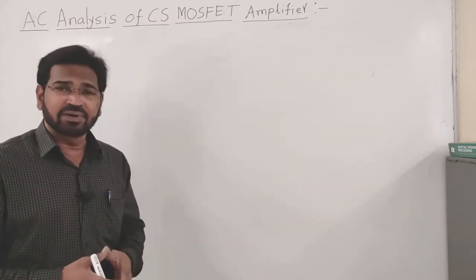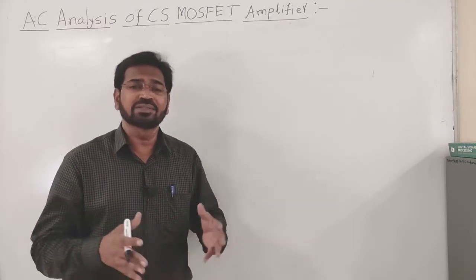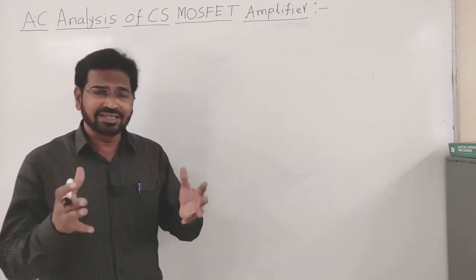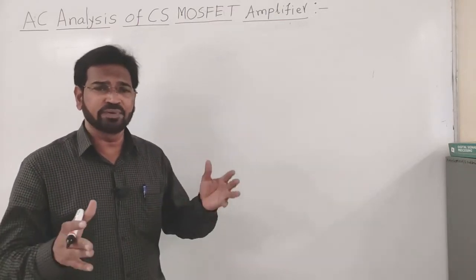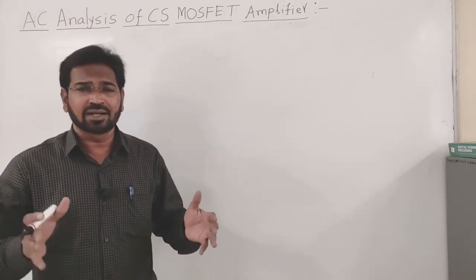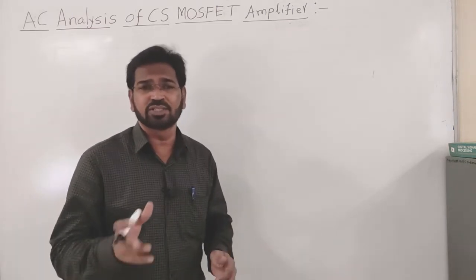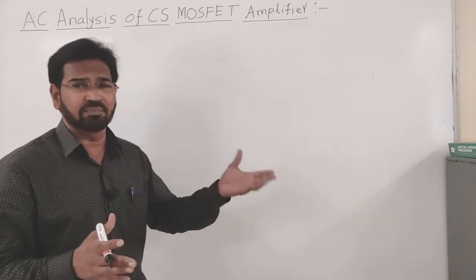Why is this amplifier circuit so important? In front-end electronics, we have sensors and transducers. These transducers and sensors detect the physical quantities. Many times we need to convert these physical quantities to electrical signals, and the output of these sensors and transducers is very weak. It needs to be processed further. So, before that it should be amplified.